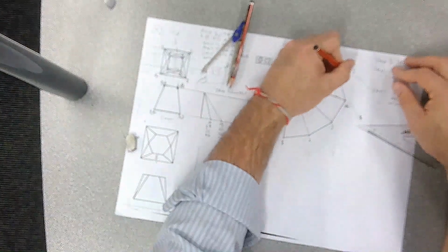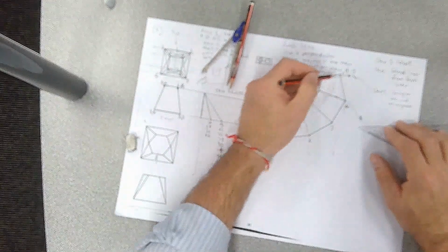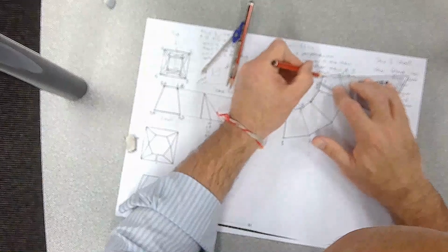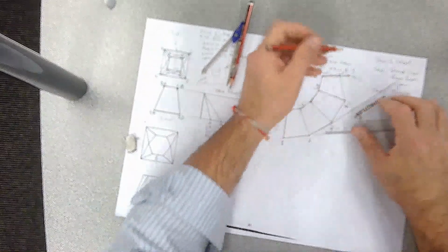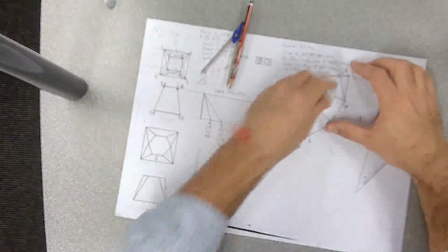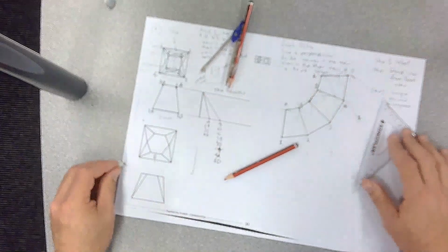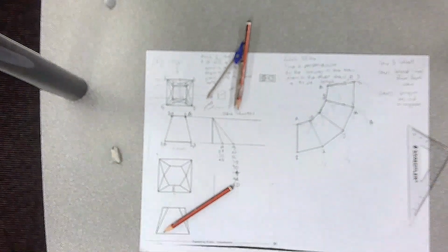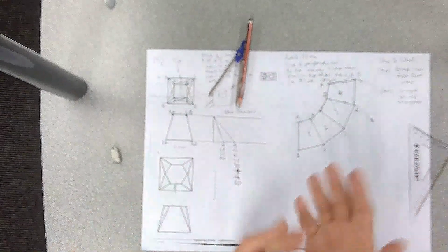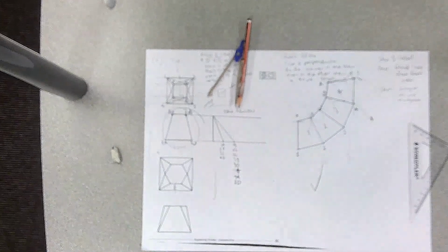Now, how did I know that I got that wrong? I know I got that wrong because this seam had to be the same length as this seam. If it wasn't, we were in trouble. So that's using a little bit of acumen in finding errors that you've made. If it doesn't look right, if you imagine folding it up and it's not going to fold up correctly, you have got it wrong. So there are your 4 panels, 1, 2, 3, 4, and if you were to close it up, you'd end up with that shape there. Tick, and you can check the answers.